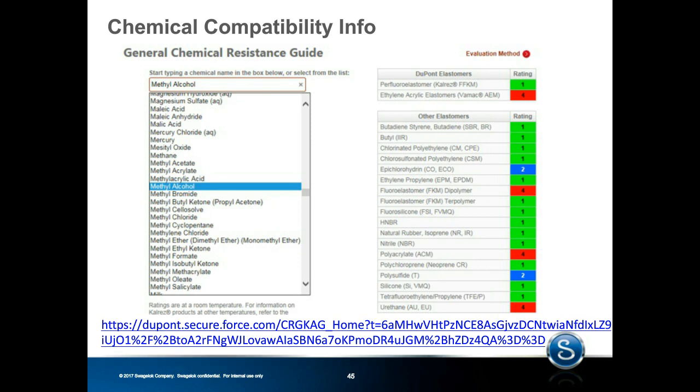The thing that I don't like about the first chemical resistance guide is that it didn't discern the difference between the types of FKM. Therefore, as an engineer specifying seals, the information isn't very useful to me because I don't know what type of FKM the data represents.